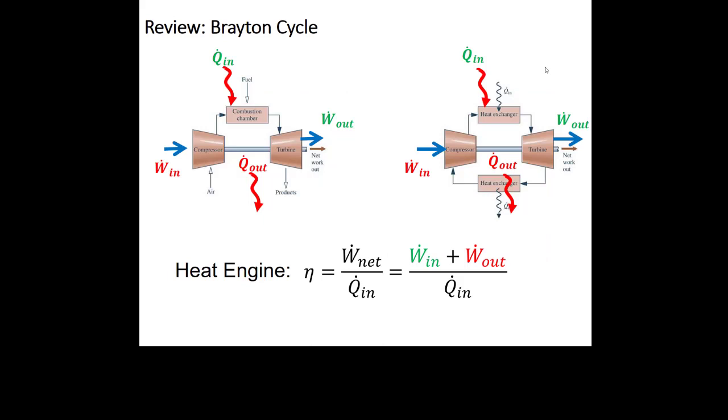So we talked about Brayton cycles, right? These natural gas power plants. We said that they're a lot like a Rankine cycle, except when we get to the question, what's the fluid, it's a little bit different, right? How we fix the states is more like how we fix the states for internal combustion engines than it was for Rankine cycles, right? But the symbolic solutions look the same.